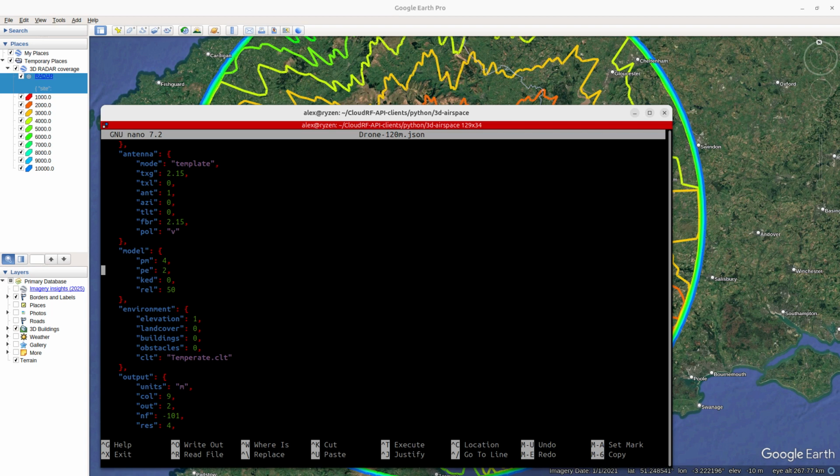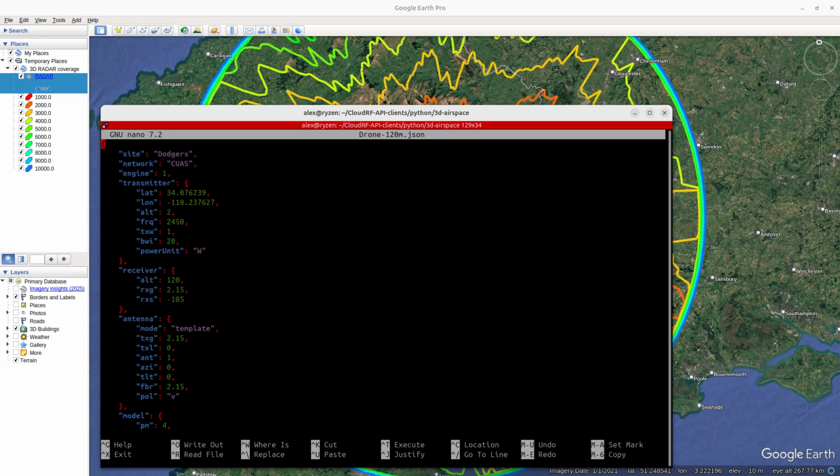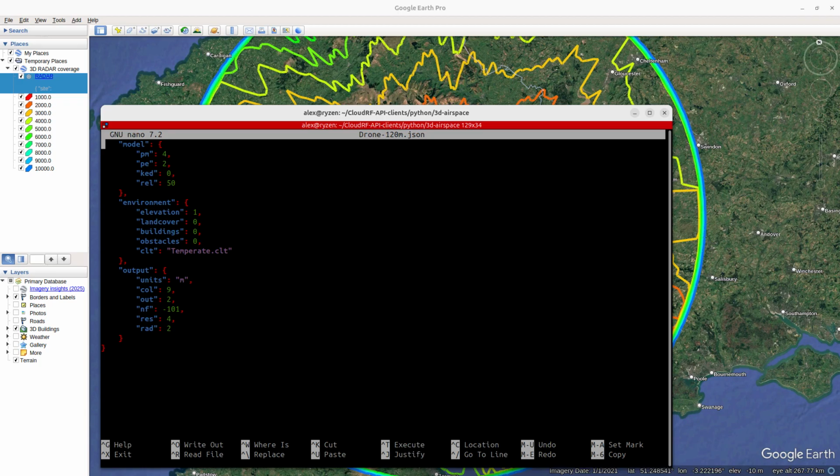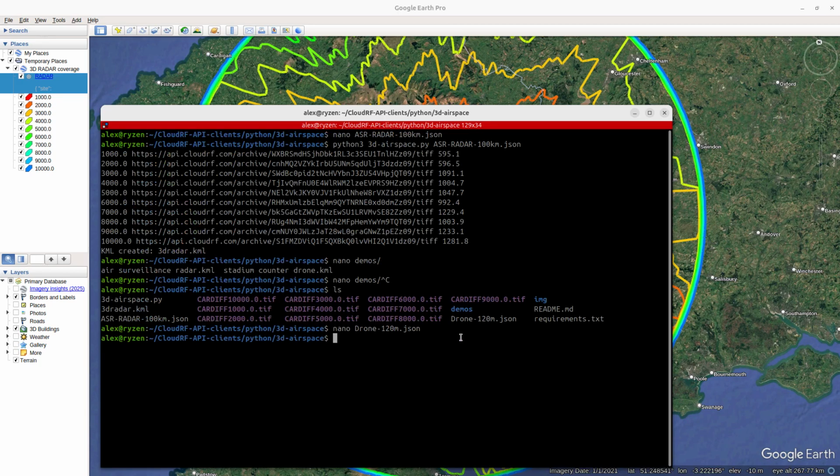And we're also using a different model here. This model is the ITU 1812, or in US standards TSB 88 model, and that's good for 2.4 gigahertz. This is a very high resolution urban one at 4-meter resolution, 2-kilometer radius, because you're not going to be detecting Wi-Fi much further than that in somewhere like LA. So let's go ahead and run this demo now with the drone.